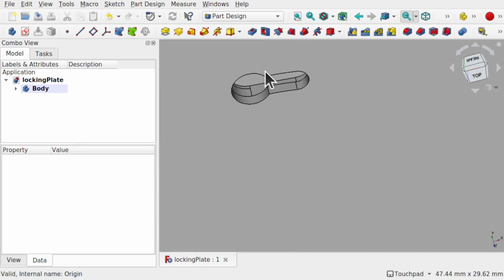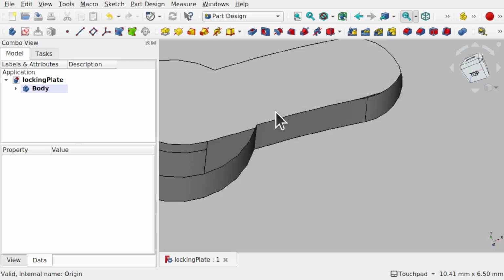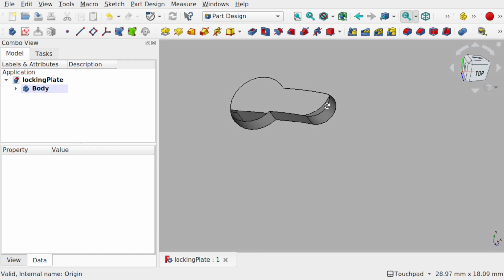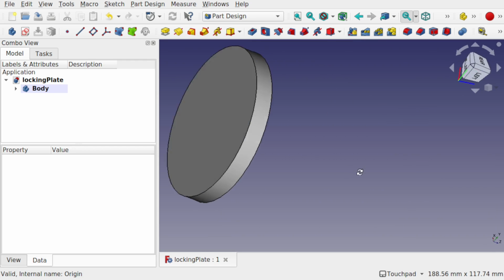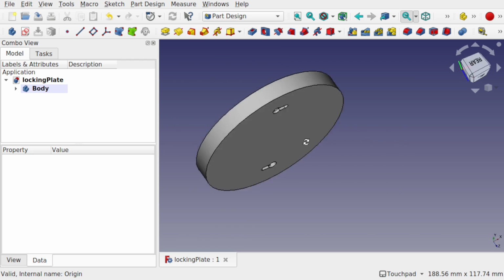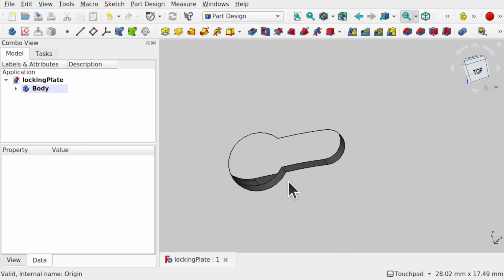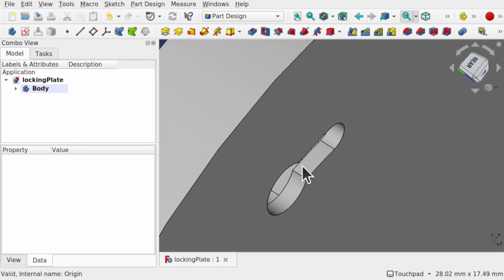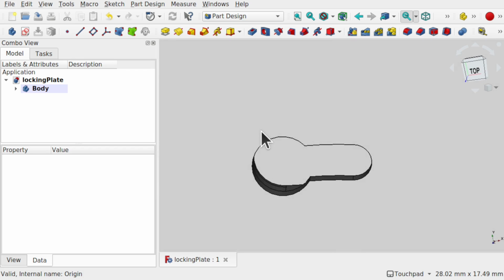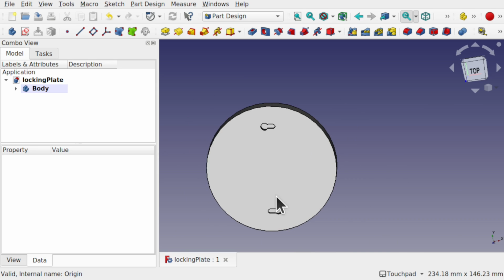After we've looked at how the pocketing works and the different types of pockets that you can do, regarding through all, two faces, two dimensions, etc., we're going to learn how to make this type of fastener. So this is a plate, and we could have something on the back of here, but this will fasten to a wall and the screws will be hidden. They'll come in here and the screws will fit into this void, but you can see we've got a lip in here, and when this is rotated anti-clockwise, then this will be locked into position.